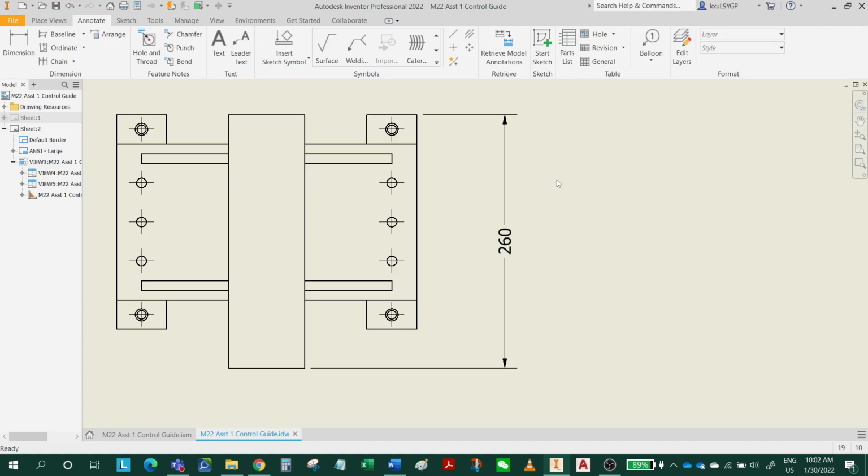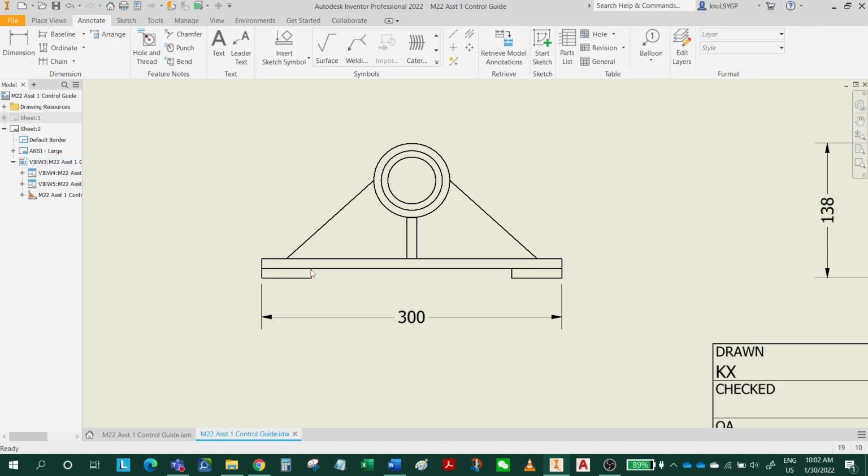Next, let's add the welding symbols according to the instructions. For position A, we have 3mm fitted weld arrow side. So from the front view, we can see that position A is here, this corner and this corner. All right. So this is the welding symbol. Right click here, and then first I'm gonna add here. So click on the corner and drag and click, right click, continue.